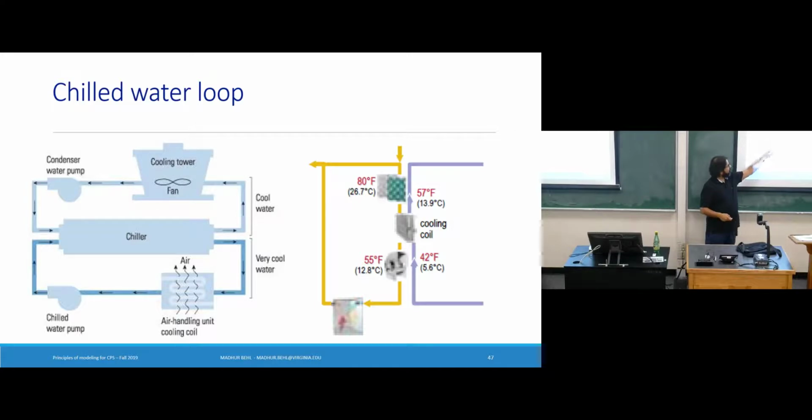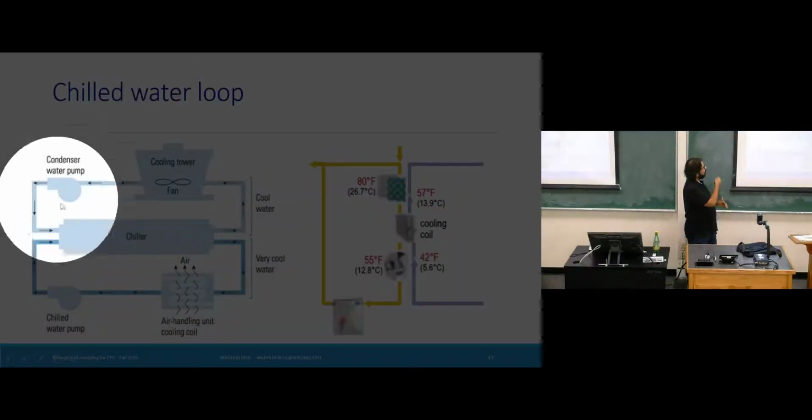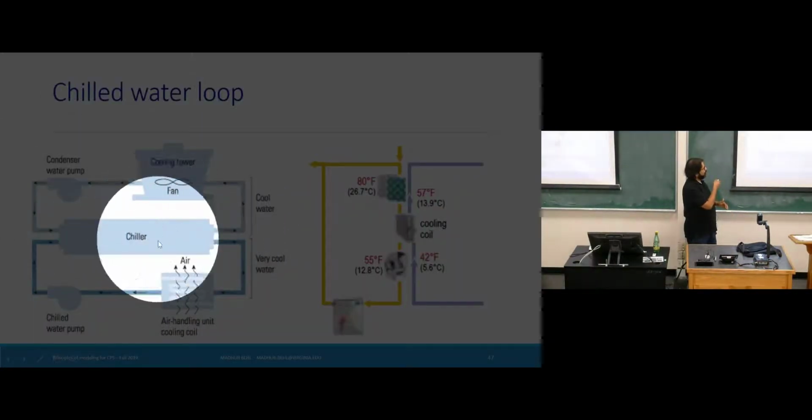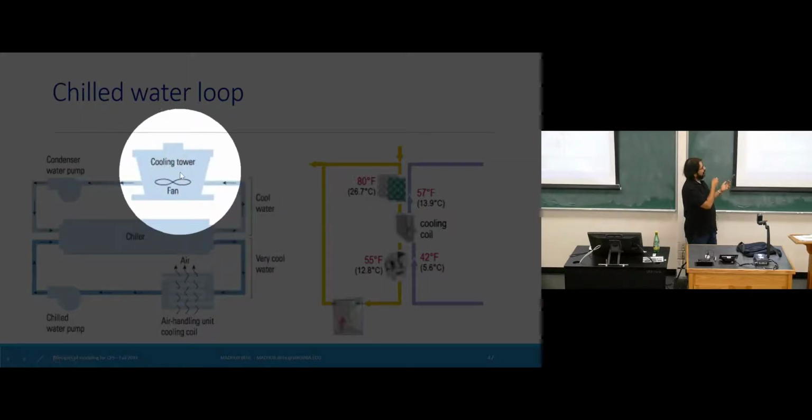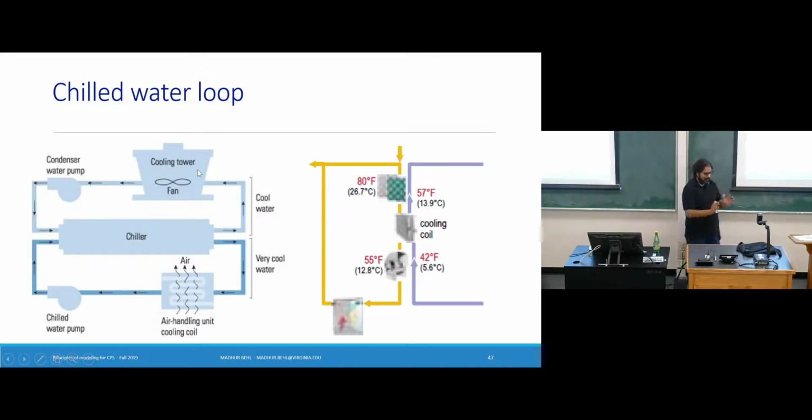It's circulating chilled water, so in some sense, it's actually absorbing the heat from every room in every building on grounds. Right? So this air handler unit could be across many, many buildings, not a single building. And then to reject its own refrigerant heat, it has another water loop where water gets the heat from the refrigerant, and then the eventual discard of the heat to the environment takes place in something called a cooling tower.